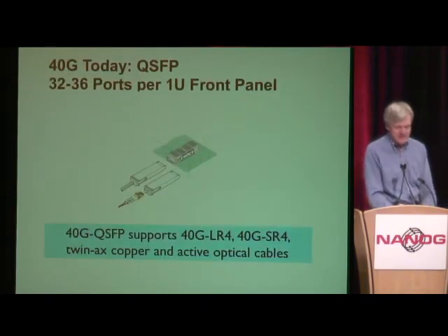Now for 40 gig, luckily, there's only one known standard, which is QSFP. This was driven initially by InfiniBand, which is a 4X kind of technology and is the form factor of choice for 40 gigabit. Again, this supports both Twinax copper cable up to a few meters and various types of lasers. The two lasers out today are the LR4, which is a CWDM that goes up to 10 kilometers, and the SR4, which goes 100 meters.